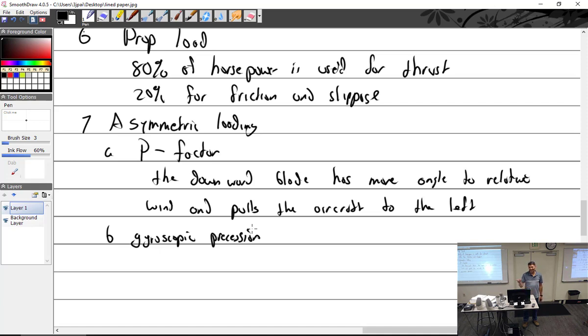They turn the other way. Engines turn the other way. So their engines are turning this way, and when the tail comes up, it's like if I push here, it's like I push, follow? Over here, which means the nose is going to go that way, so you need left rudder. And when I say rudder, you don't give it a little bit. I mean, it's a big deal. When you're getting your tail wheel checked out, you learn to dance on these rudder pedals. It's a lot.